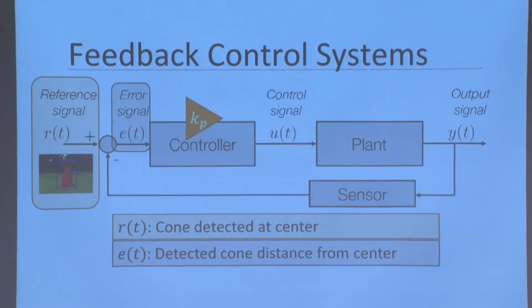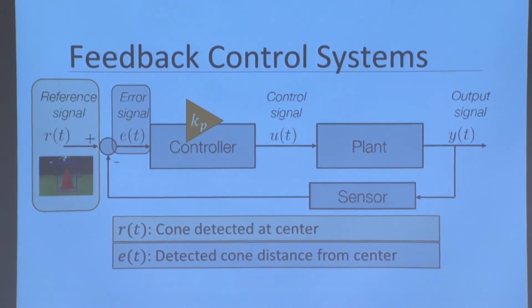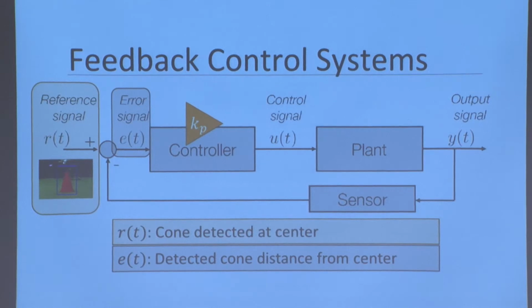We're going to do a controller. So in this example, say we just use the proportional control. I recommend using that first, making sure you have the system working. Think about improving the control later.